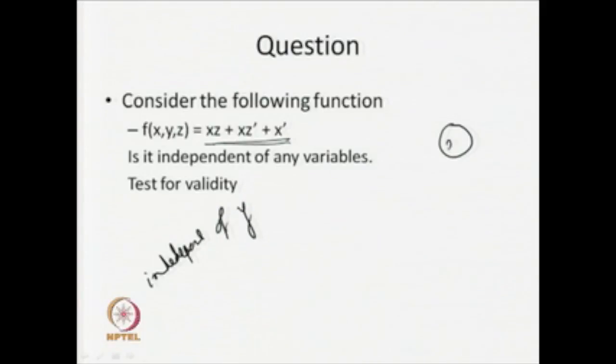Okay. So, x may take value 0 and x may take value 1. When I construct it, when x bar equal to 0, then my functional value is 1. Now, when x equal to 1, then we have to take a decision on z. When z is 1, then x z is going to give me 1, and when z is 0, x equal to 1, z equal to 0 is going to give me 0. Eventually, you can see that this is a redundant test, so I can remove it.